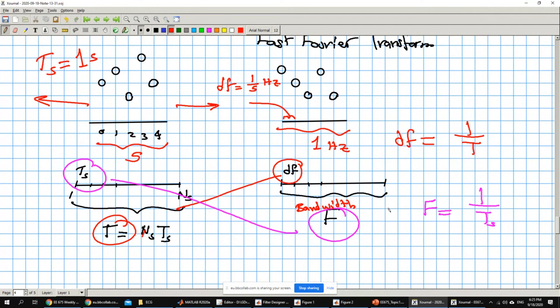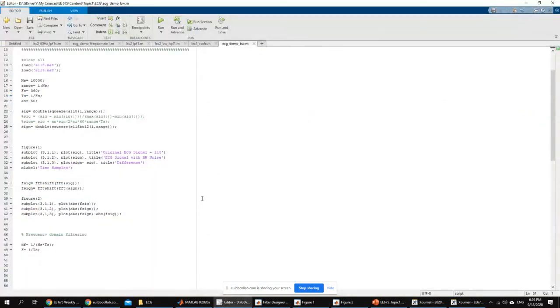That's why we say that if you have a frequency above the sampling frequency over 2, you're going to be aliased. You're going to have improper sampling. So you have to make sure that all the frequencies in the signal are below f sampling over 2. Or in other words, per Nyquist, the sampling frequency should be twice the maximum frequency of the signal. Okay, so this is just a reminder of the Nyquist frequency.